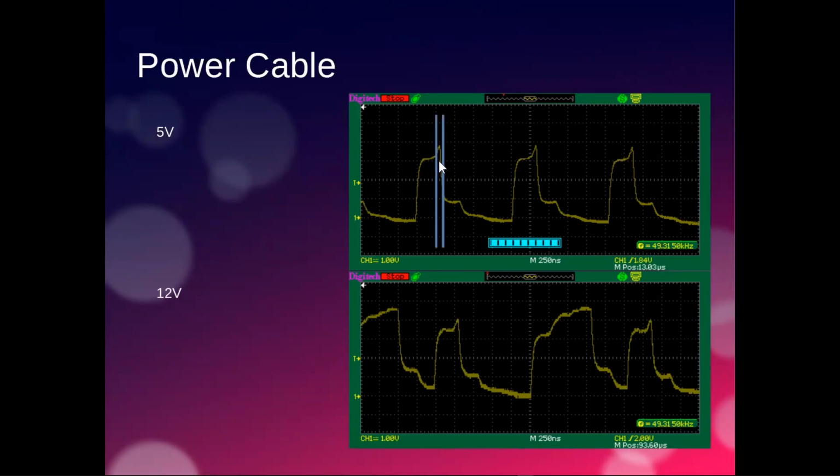So take the 0 here. The 0 here is triggering at this point here, assuming that this chip is getting 5 volts. Of course, it's a 5-volt pixel, so it's probably not getting 5 volts. So it's probably actually triggering a bit earlier. But if it was getting 5 volts, it's not going to actually see the rising edge until this point here. Now,